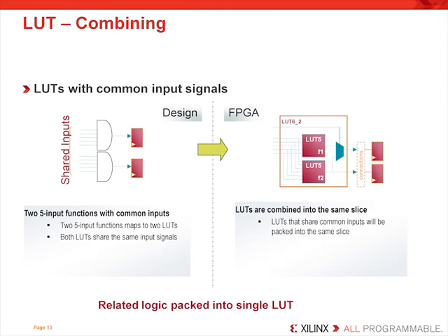It is also good to note that the implementation tools automatically look to group LUTs that have common inputs into the same slice. In this example, the tools took two 5-input functions that have the same inputs and then grouped them into the same slice.